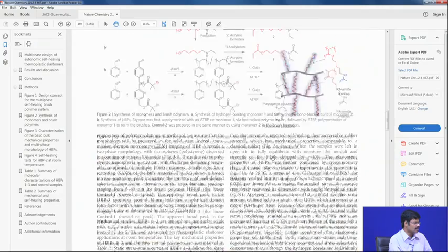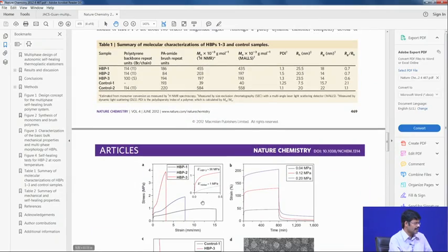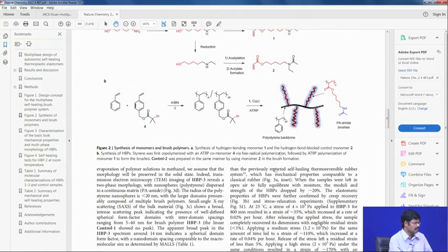So, you may make the material tougher, that means the material can actually stretch to a higher strain, and also stiff enough because the material has this backbone which is your polystyrene. So, that means it is a kind of an elastomeric material, and this is also stiff plus they are stretchable. So, both the properties are actually present. So, this is an example in which your structure dictates the property. Along the way we will discuss more examples after, but this is the power of ATRP, that is the take home message from this particular paper.